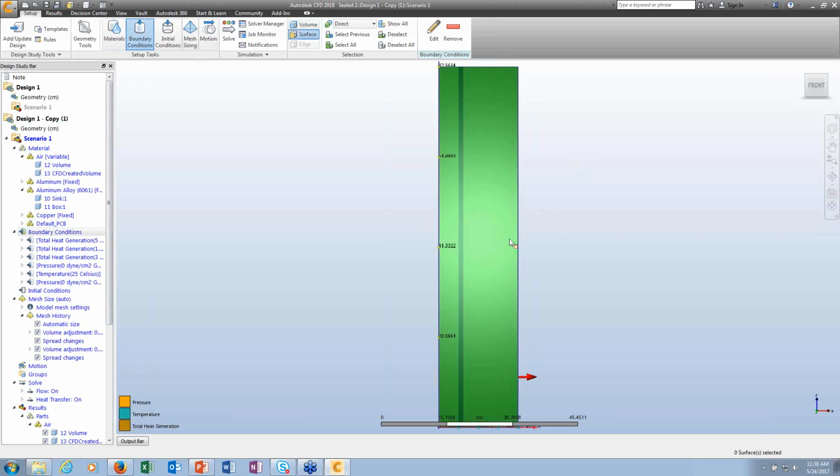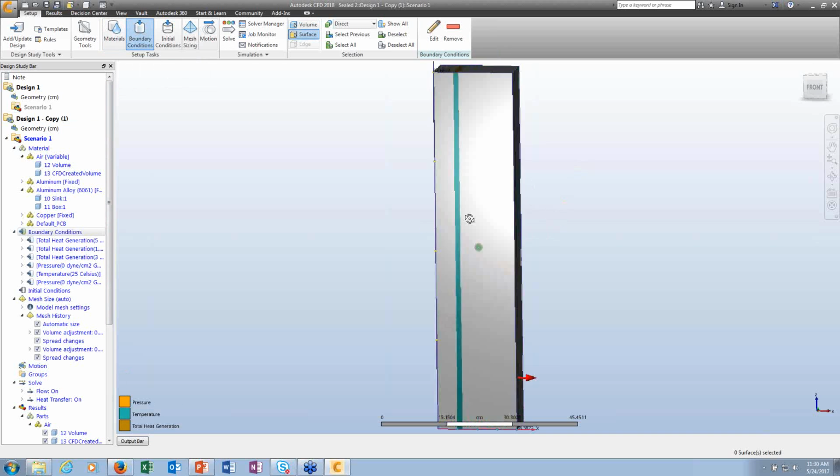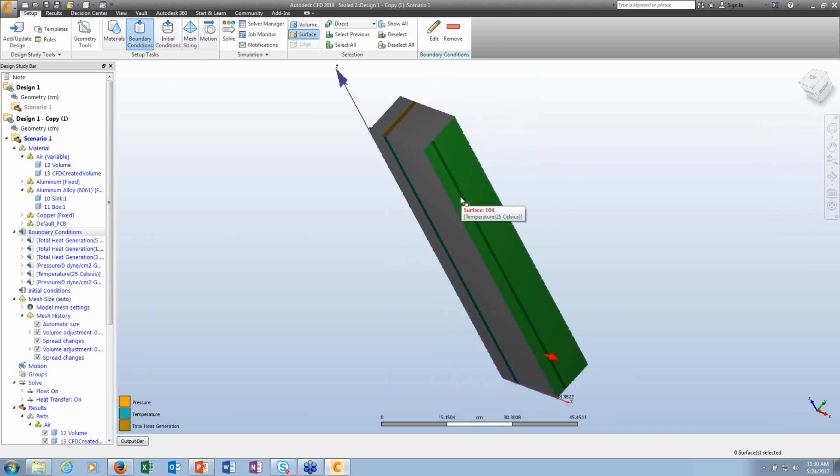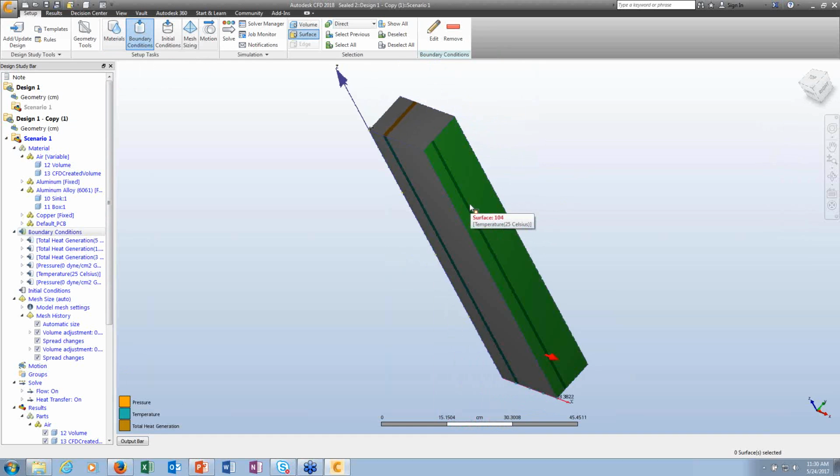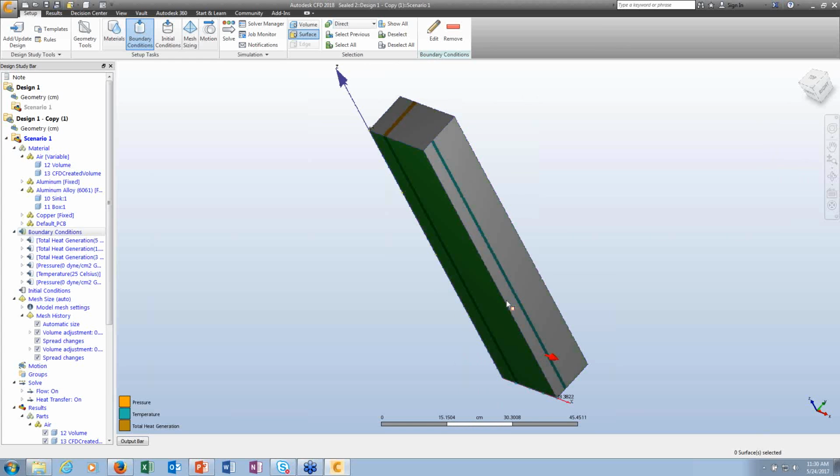as far as the bounding box, what we have is temperature on the 4 sides, and we're going to use that for the radiation. We used radiation in this case. In an analysis like that, you do want to use radiation because it could affect the temperatures up to 30%. So you definitely want to use radiation.